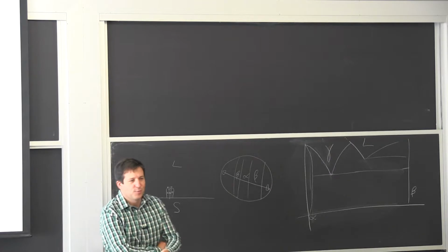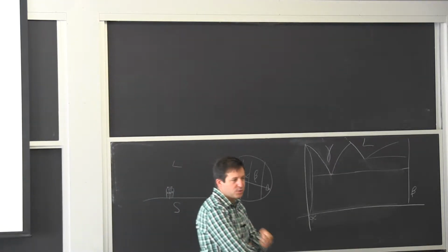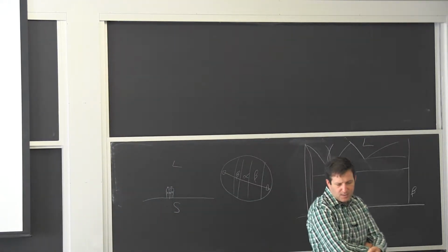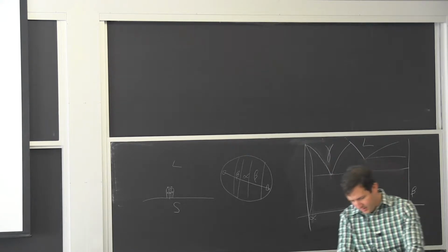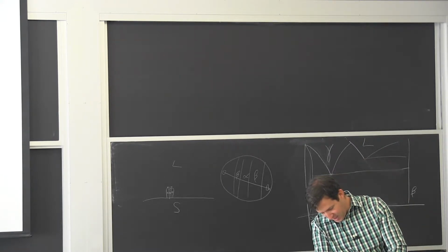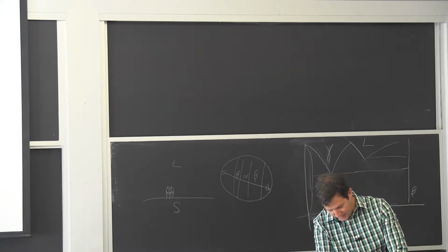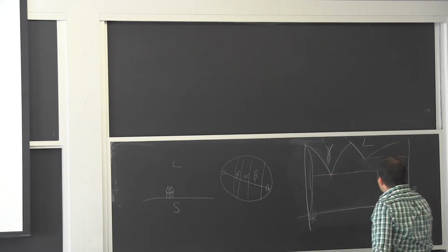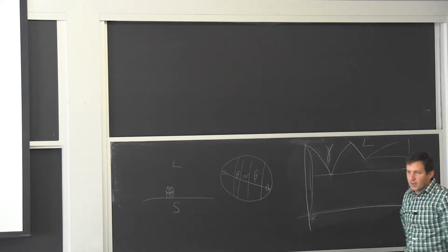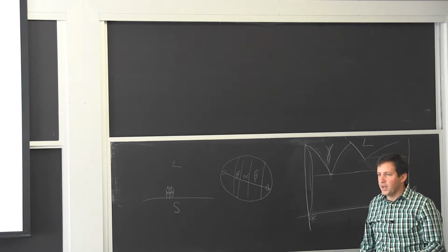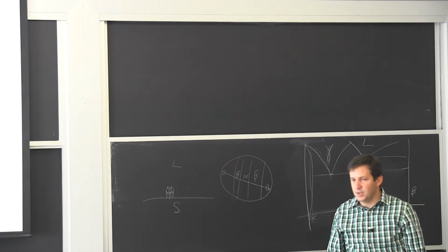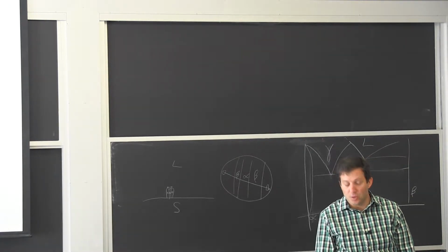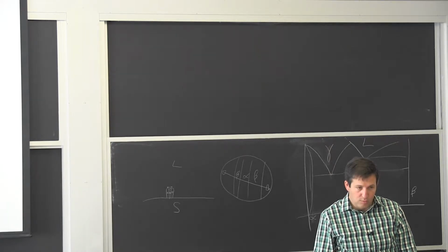It's only going to make it softer. That's also the same for stainless steel. If I take this beam, and it's an austenitic stainless steel, essentially a steel that remains a single phase, I can't make it stronger by heat treatment. It's just not going to happen. So the only way to increase the yield is by cold working.